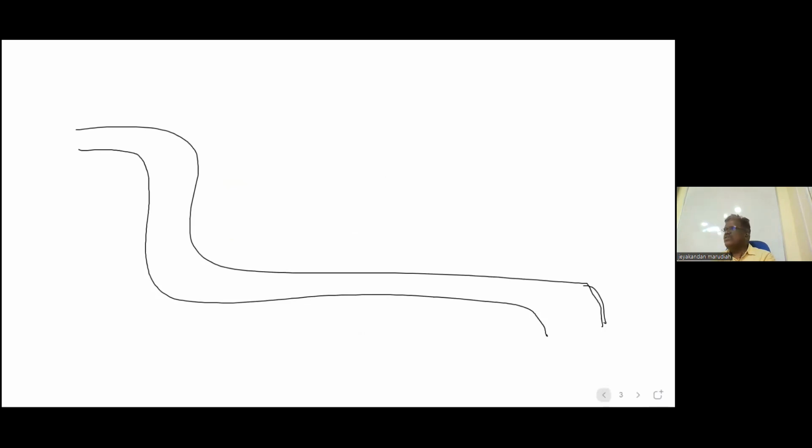Now, suppose this is my circuit. Even in a circuit, the entire circuit we cannot do. Some selective areas only we will do NDT. These selective areas are called CML. CML means condition monitoring locations. In CML, we can do any examination. It is not restricted to only RT or UT. Suppose we have found a fatigue crack, what will we do? PT or MT. Whatever type of damage mechanism, they will mark CMLs based on their previous experience. But every time when they are going for inspection, based on the current condition, they can change the CML.